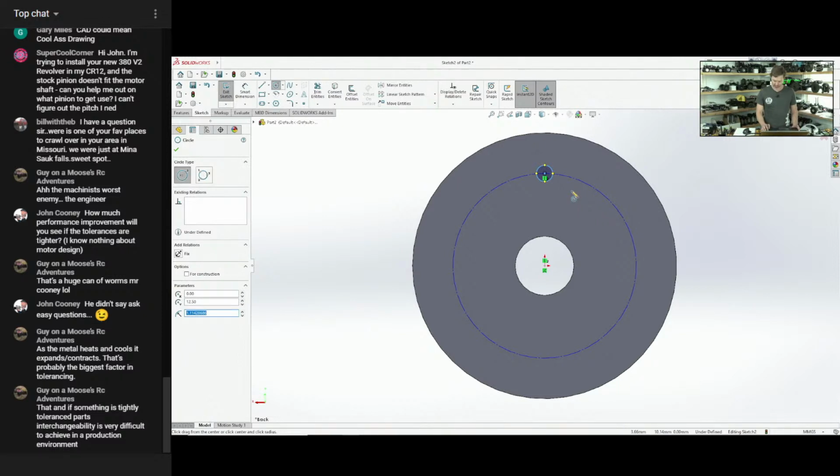So we would do 2.75, that needs to be divided by 2, so 1.375 millimeter if I was going to do a roll form thread. If this was going to be a cut thread, it's going to be a 2.5 millimeter hole, so 1.25 on there. It really doesn't matter. We can always just do call outs for threaded holes down the road.